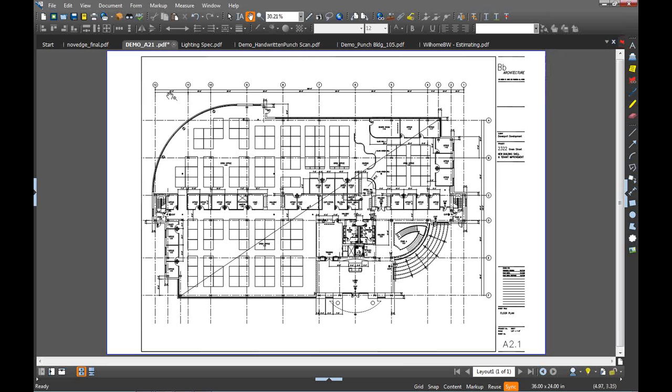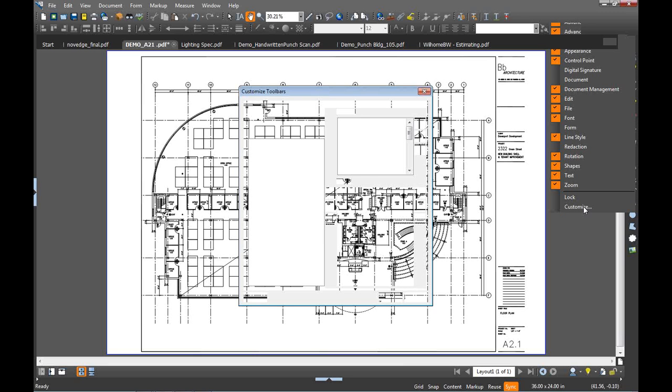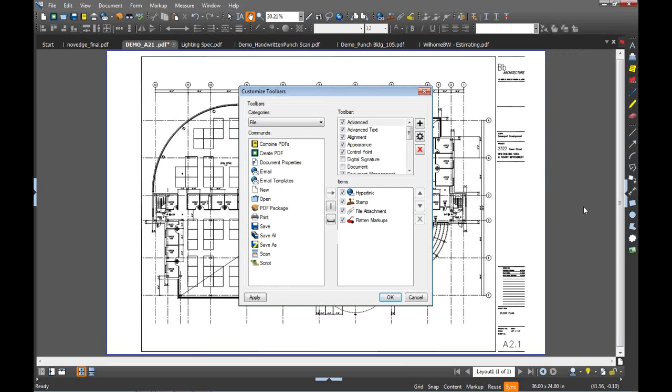As I continue to walk my way around the interface, you'll see that we have, again, all these menus up here. Bluebeam is a very context-driven or right-click-driven application. By right-clicking or hovering over icons or tools or menus, you get to see a lot of different information. So I can right-click anywhere in this gray area and see any of these menus that I maybe do or don't want to see. I can also come down here and possibly completely customize a menu to make up the exact or precise menu that I want to see and only have that menu available for me.